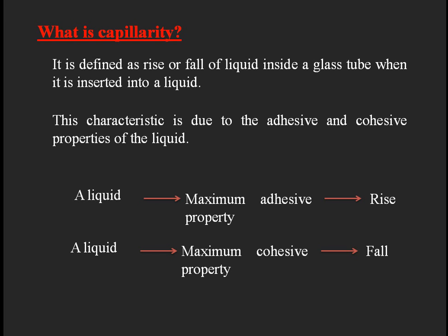Similarly, if the molecules have more cohesive property, which means all the molecules will try to compact together, the attractive forces will be more than the repulsive forces between the fluid molecules. In that condition, there will be no sticking of the fluid particles to any other external body. So the fall of the liquid will occur inside the glass tube whenever we insert it into a liquid which has maximum cohesive property.